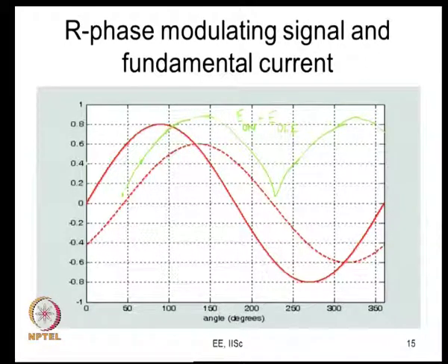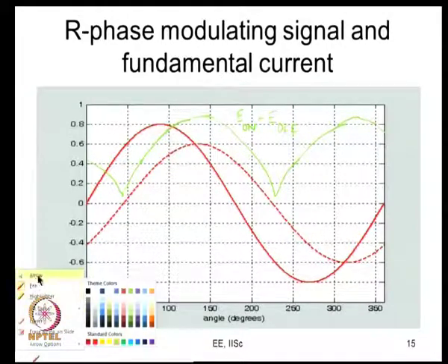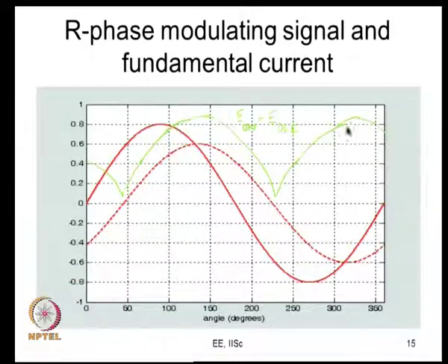So, this is how the nature of variation of E on and E off is going to be. So, how is this variation? You can say it could be roughly sinusoidal if you ignore certain things, if you say that this is proportional to the current. So, you have certain average value, you can evaluate certain average value, and this is the average value. You would take it as the average switching energy loss and multiply it with the switching frequency to calculate your switching loss, the power that is lost here.